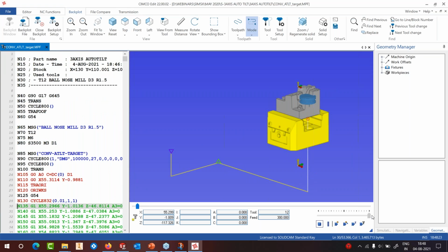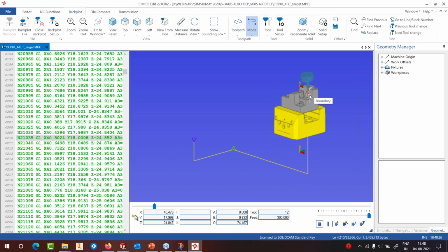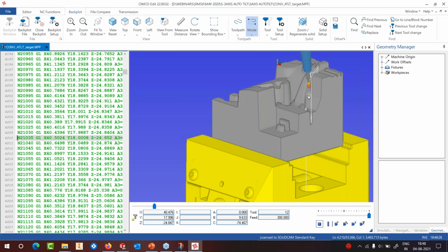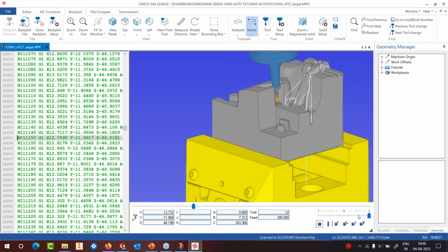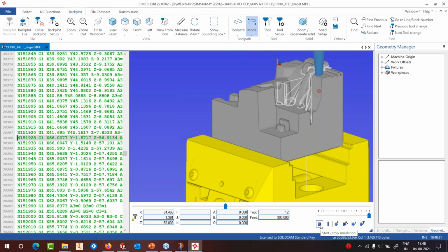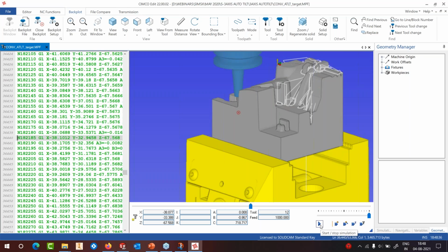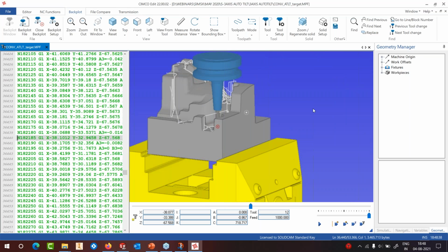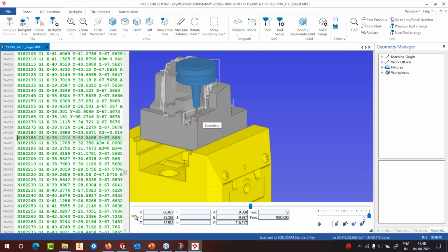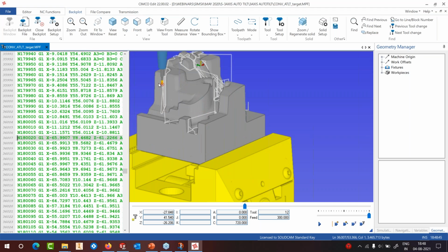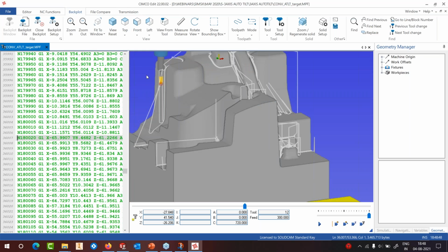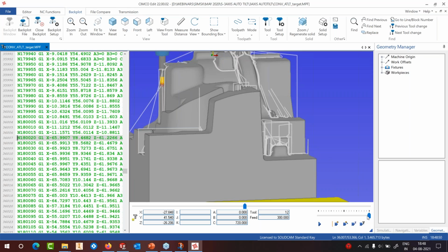Of course, you can see now I have got, wherever it comes precariously close to the area, you can see that it tilts automatically from a simple 3-axis. From a simple 3-axis, it can convert the toolpath to 5-axis. So I'm going to cut down on the speed.